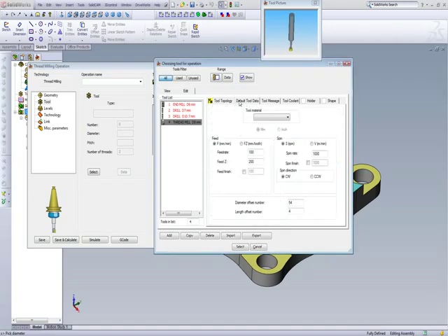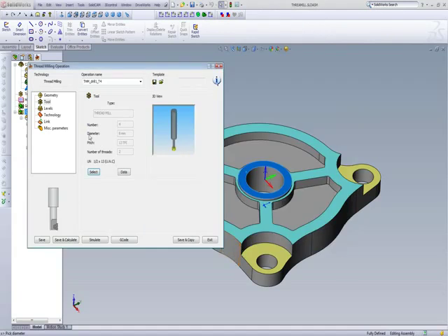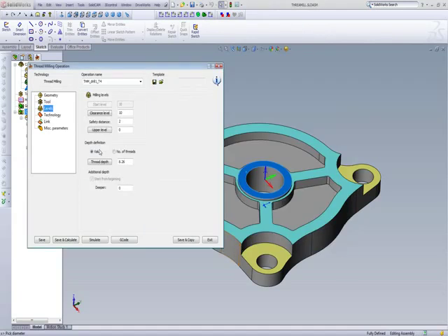In the default tool data, the data is exactly like any other end mill. I'll simply select my tool, and then we'll go to our levels. We have our upper level on the top over here, and then we have our depth definition. We have two ways of defining our depth definition. One, either the actual depth of the hole itself, or the number of threads I want on the wall itself. Either way, whichever one is necessary.